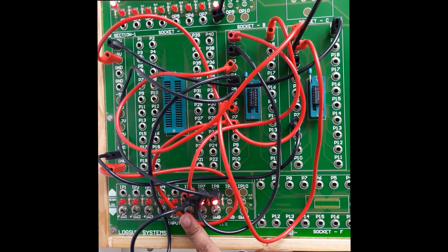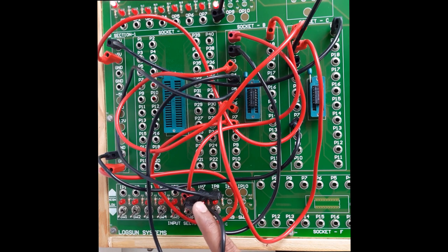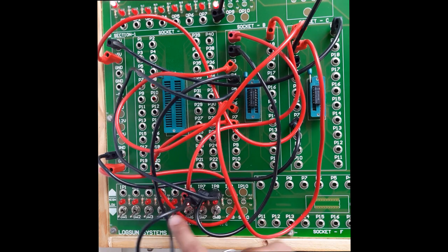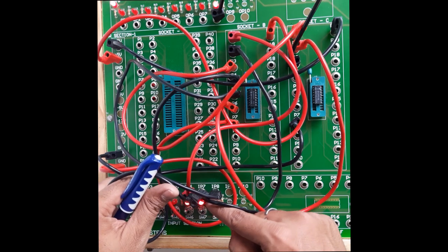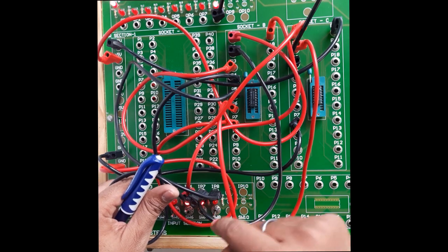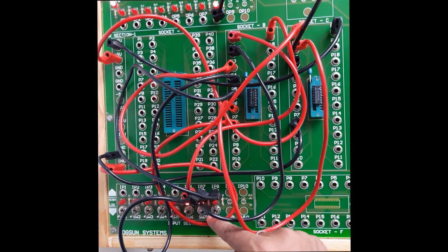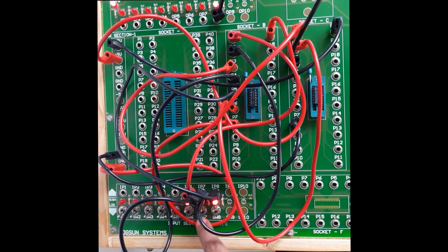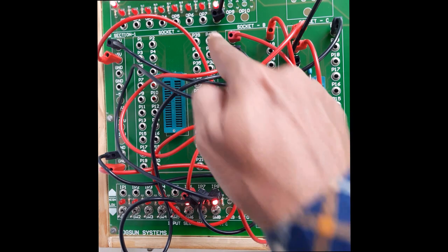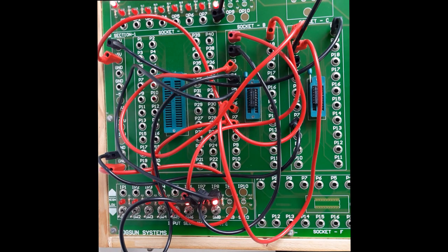Now I am considering 6, so 1 1 0. For 1 1 0, if you consider this LED, both LEDs are okay, and the third one is 0. So 110 is nothing but 6. For 6 also you are getting the proper output. Now 7. So all LEDs on the input side are high. Then for this, your expected output should be high. Now I am considering 5, 101, so it is low. So in this way you need to perform the experiments on the digital trainer kit. Thank you.